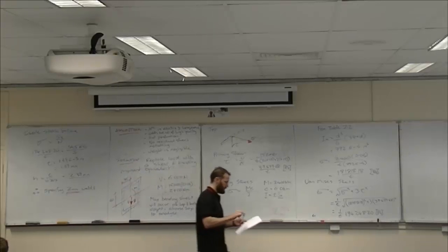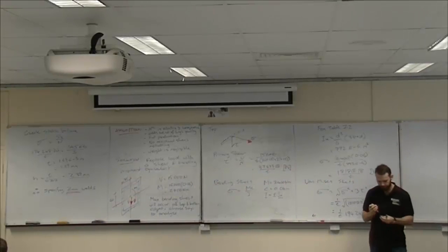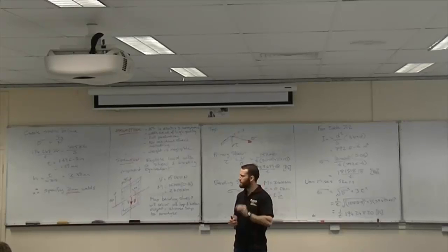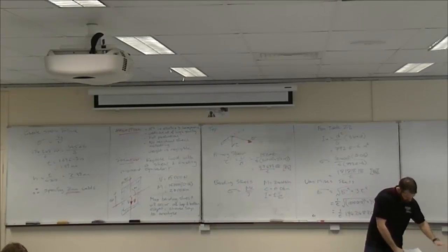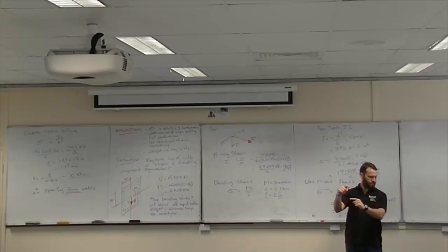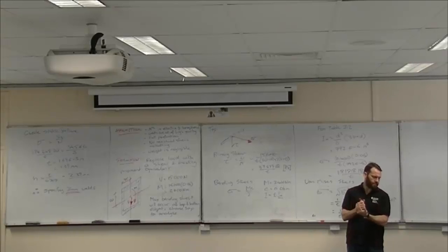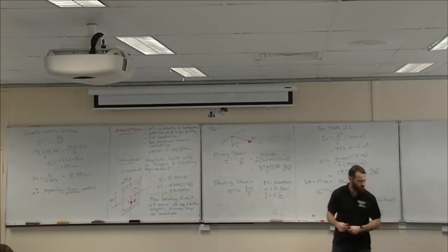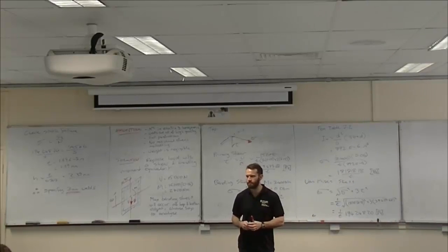There you go, so let's go back to our engineering judgment for a second. Think about what a 3 millimetre weld looks like. That's pretty small. Nice little tight weld. And what's the dimensions of our thing? So we're talking 120 mils, I don't know, I don't rule, but that-ish, by 70 mils, that-ish. And 160 mils, that-ish. And we've got 15 kilonewtons, which is the same as 1.5 tonne hanging off the end of it. So about that 1.5 tonne, you've got 3 mil welds around there.